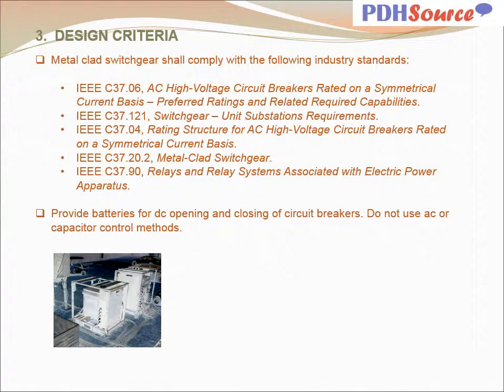Provide batteries for DC opening and closing of circuit breakers. Do not use AC or capacitor control methods.